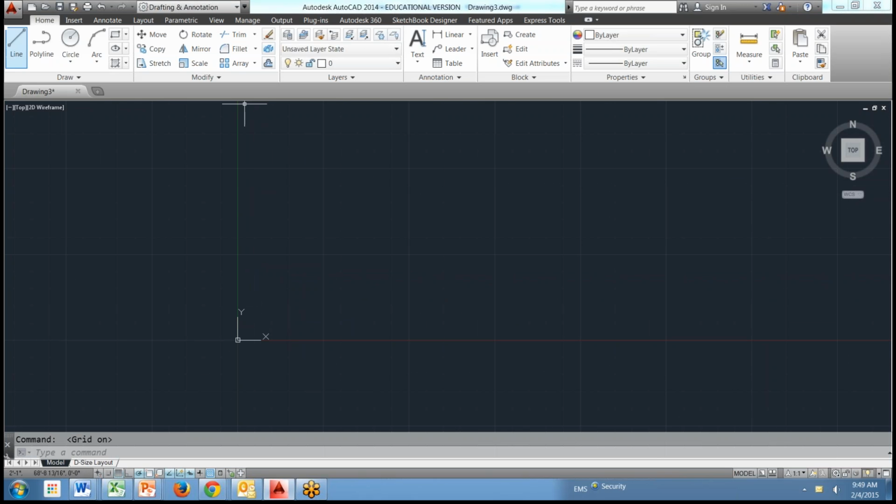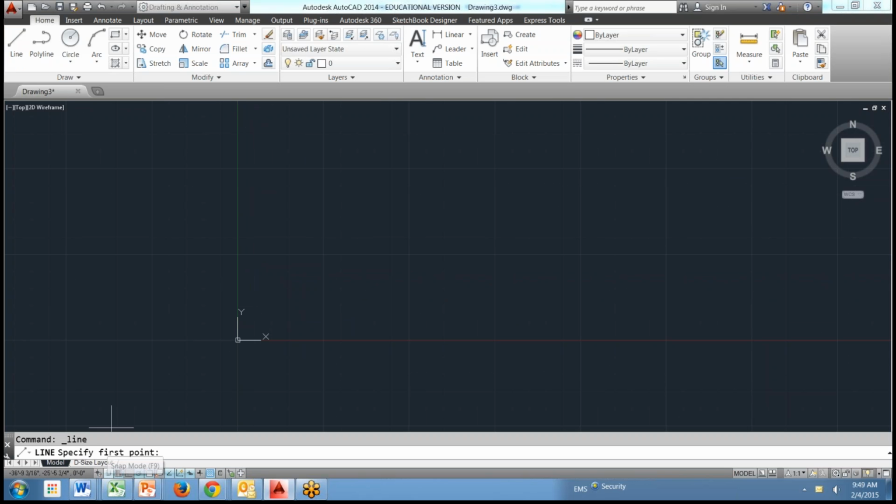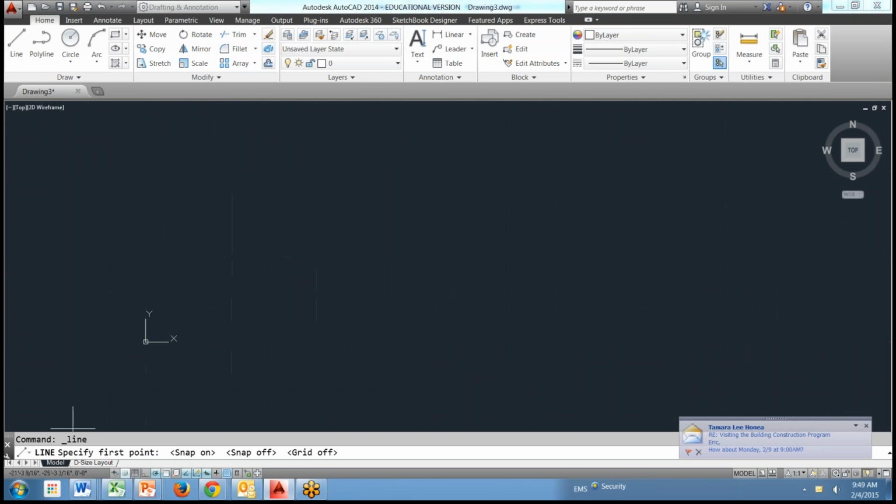If I have my grid on and I click on snap mode, you'll notice that it pops, and I'm going to pull right on in here. See how it jumps? And it jumps per inch. Okay, so you'll see that that's 53 feet 1 inch, and I move it over, and it's going to jump to 2 inches. See how it done there? 2 inches. Now I can drop to 3 inches. Okay, so I'm going to a snap mode of 1 inch. So I'm going to turn that off. I'm also going to turn my grid display off. I generally don't use that a great deal.